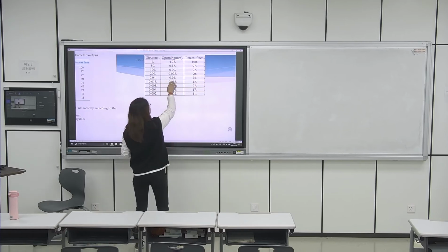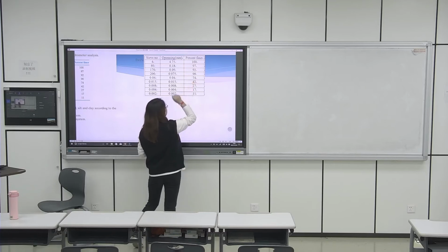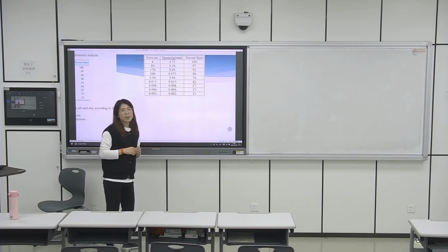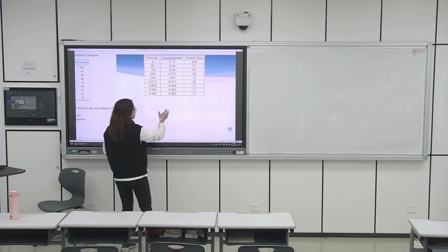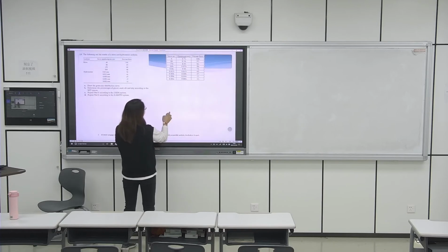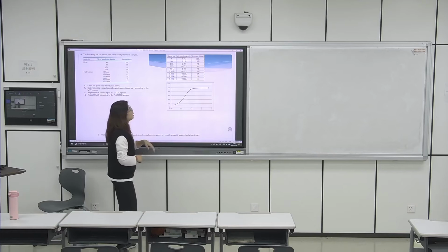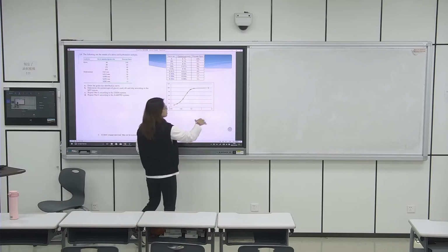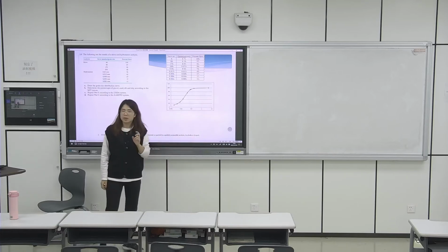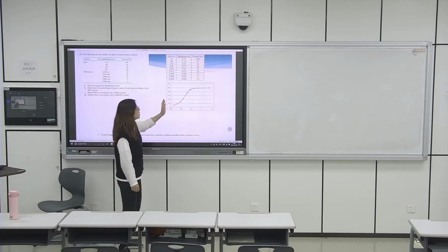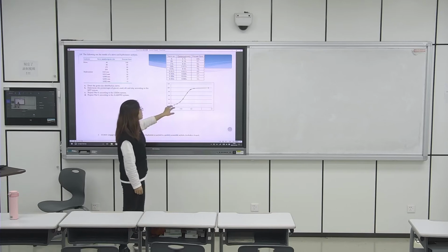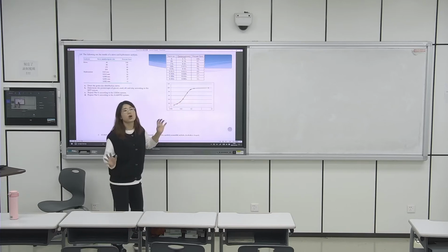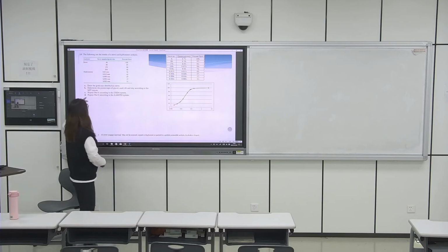So then you know the opening and you know the percent finer, and then what's the particle size distribution curve? The particle size distribution curve is actually the relationship between these two, okay? If you plot, the x-axis is the opening, or we say particle size, and the y-axis is the accumulated percentage. Then just plot those points here, that's all. So then let's see B, C, D.